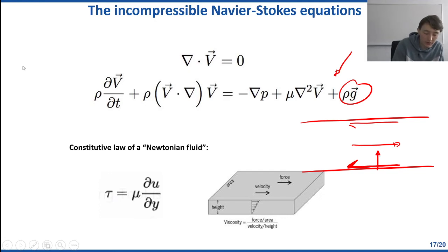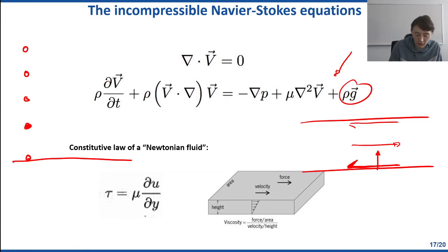So now, suppose that I have this very coarse mesh, which means that my first degree of freedom away from the boundary is going to be here. And this shear stress is going to be the derivative of my u with respect to that height.